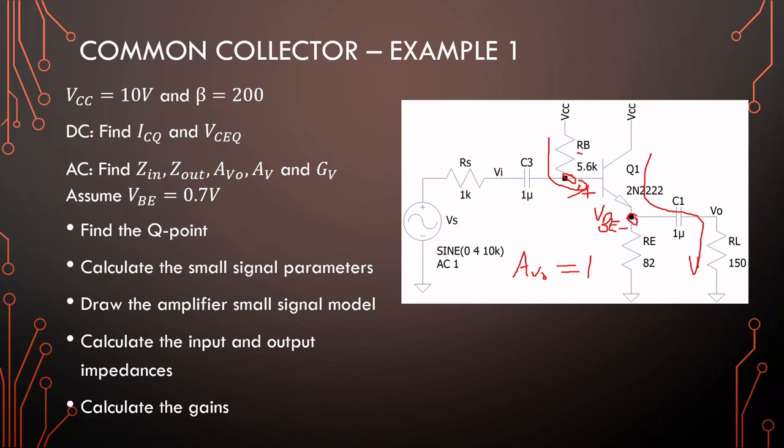And we know that a base bias has a very large resistor value, and you can see that in this problem it's already a very small value. So the bias can decrease your input impedance by quite a lot. So that's why I went to a base bias scheme, and we have an emitter resistor for stabilization.